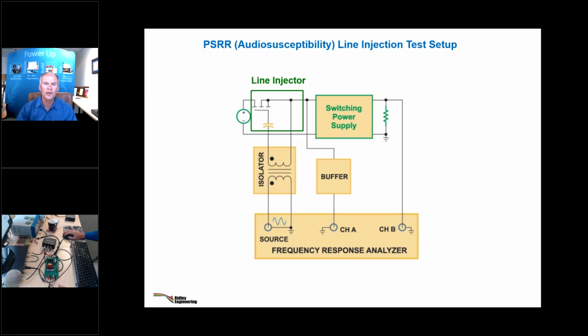It works for up to a certain amount of power level and certain voltage, where you just build kind of an amplifier, which is a follower, because we want current driving here to be able to drive this input. So you just go through the isolator from the source, AC coupled to the gate of a FET, and then this FET will have a gate to source voltage dropping across it. And then you can apply modulation to the input of the power supply. So this kind of works. It's a technique we've used for many years.